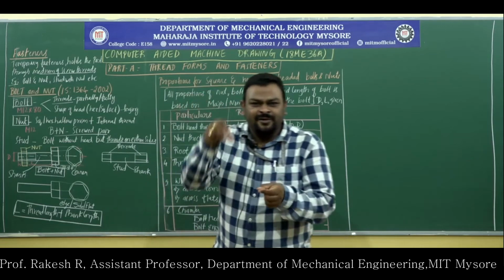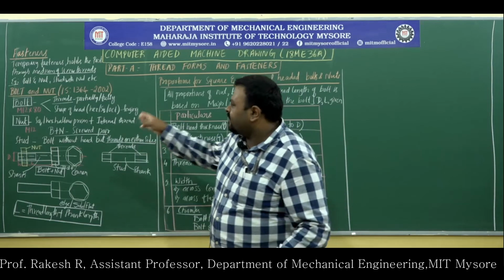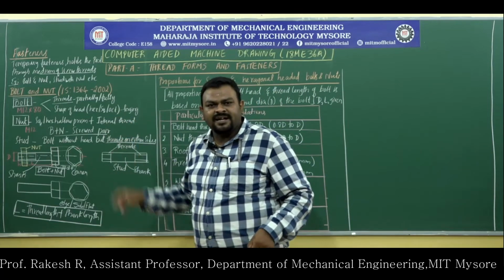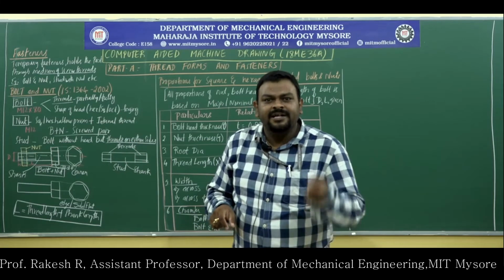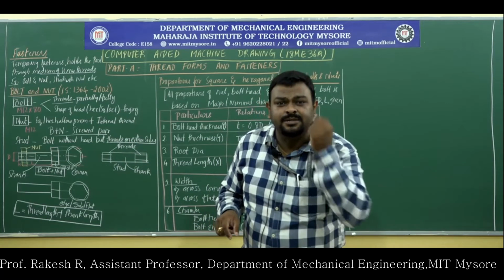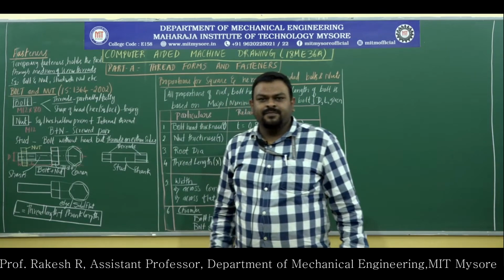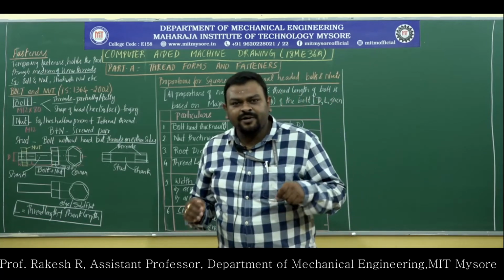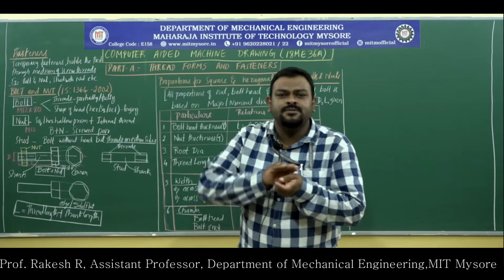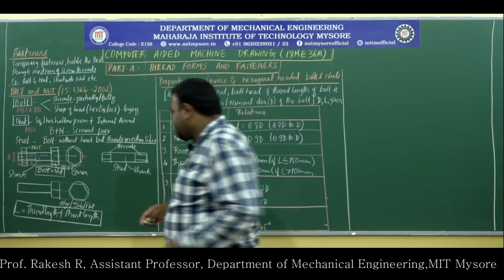So, if you use hand instead of spanner, the material of the bolt and nut, sometimes if it is a mild steel, if it is having any sharp corners, then your hand will get worn out. In order to make a flexibility for a design, in order to make the surface smooth, what we will do is, we will be introducing a chamfer.